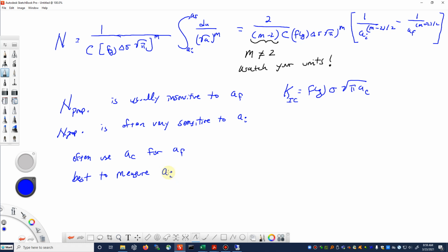So when you do a stress controlled fatigue test, like the rotating bending test, that's over when it fractures in half. So the crack propagation is really kind of built into that, but the crack propagation life is fairly small in comparison to the total life of the component. When you do a strain controlled test, you often stop that test when you experience a drop in load. The drop in load is caused by a crack or multiple small cracks initiating and being present on the surface. If you can measure those, then you can use that for the initial crack size. If it's not a safety critical calculation, then maybe you can use 1 millimeter or a half millimeter initial crack size, and that would probably give you a pretty good estimate.